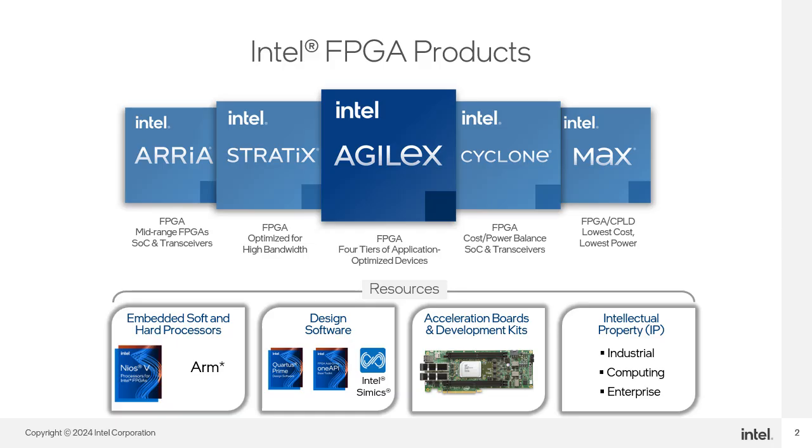The Intel FPGA portfolio supports this transformation, including discrete and integrated FPGAs that are expected to improve processing efficiency, task specificity, and connectivity. Intel FPGAs can provide a variety of workloads in network processing as well as compute and storage acceleration. FPGAs are mass-produced, standard product ICs that can be reconfigured in the field to accelerate virtually any digital algorithm. They offer greater throughput, execution speed, and energy efficiency than CPUs on computationally intensive parts of algorithms, but with the ability to adapt quickly to changes in algorithms, data patterns, or performance needs.